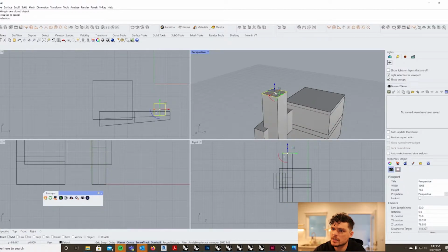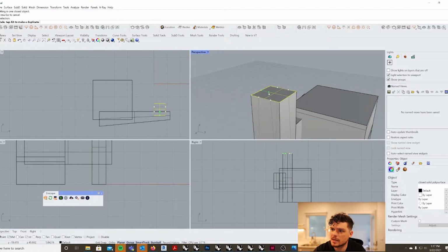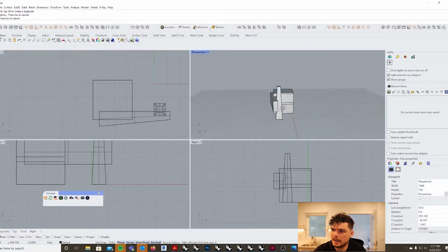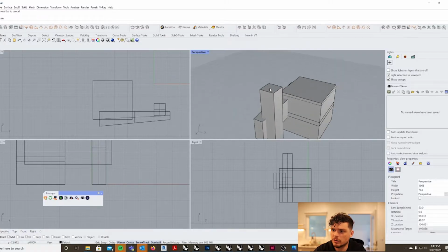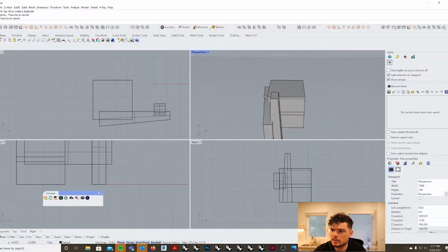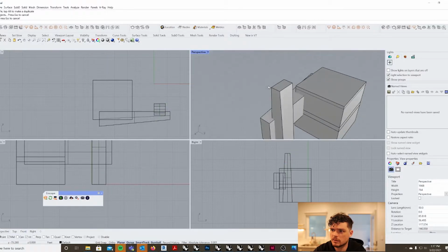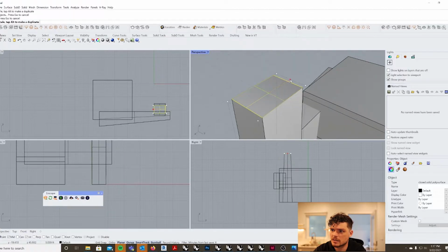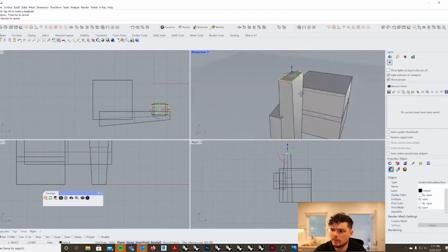What's cool too is you can select the top and you can actually scale this, and then you can get an overall tower taper really quickly just by going select shift. And let's say we didn't want to do it on every side. We just wanted to do it on a couple, on two, then I'm only moving this scale button here and do stuff like that.